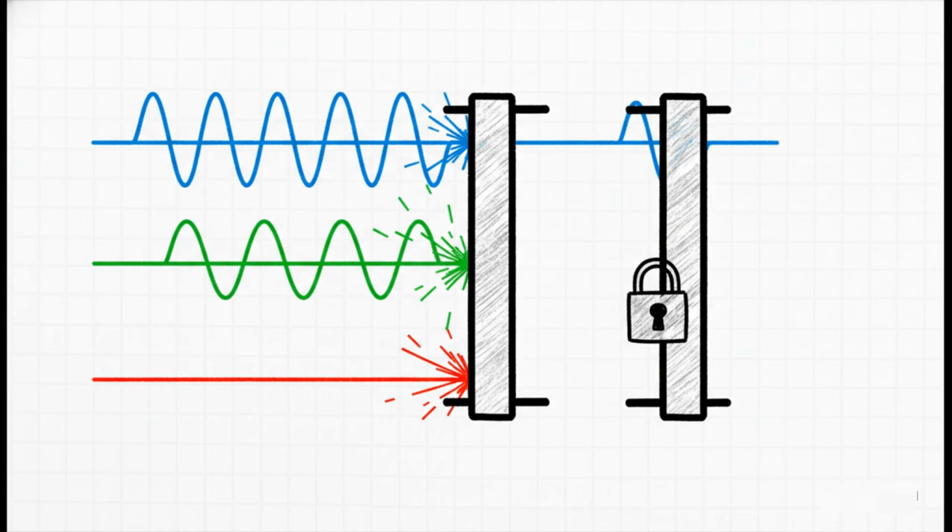So the most crucial point to take away from this is higher frequency equals lower reactance. Capacitors basically become superhighways for high-frequency signals, but they act like giant roadblocks for low-frequency ones. And what about DC? Well, DC has a frequency of 0, right? So the reactance is infinite, a total dead end. And that, my friends, is our first major clue.